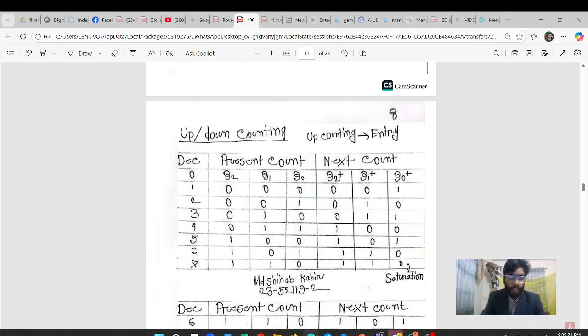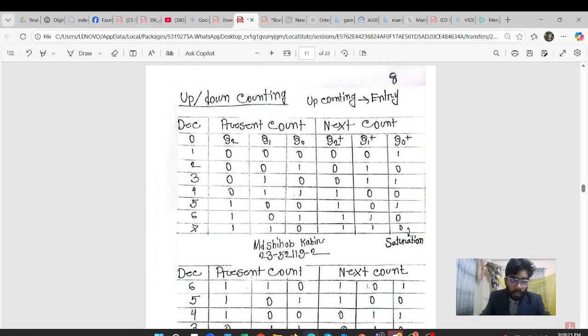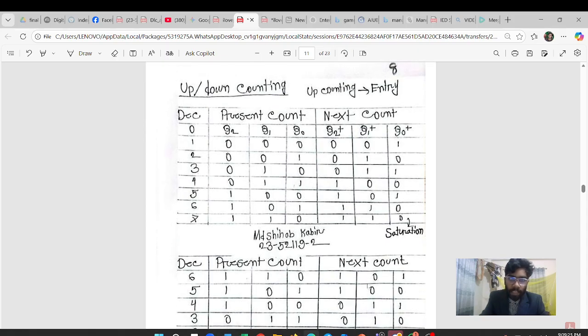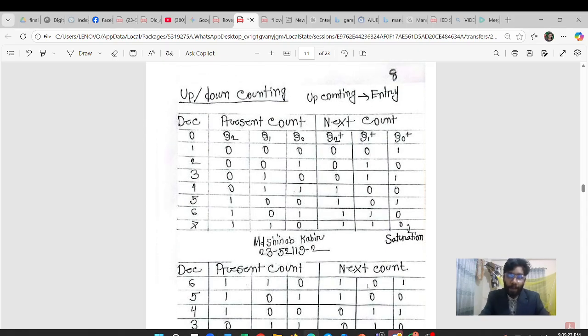The last step is that I used an up-down counter, and it is a simple logic circuit. When a car enters, a sensor sends a pulse to the up pin, updating the number by 1.